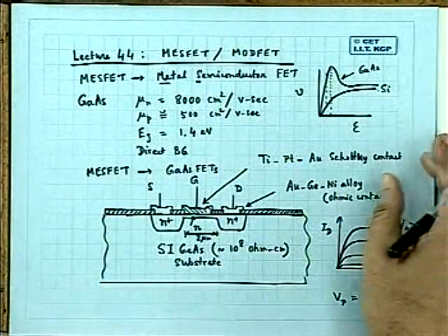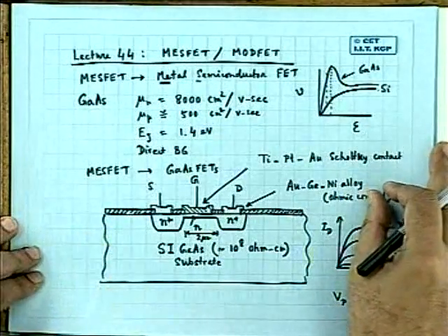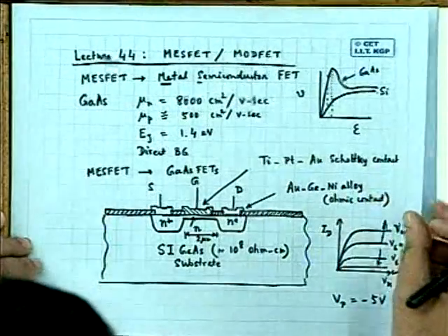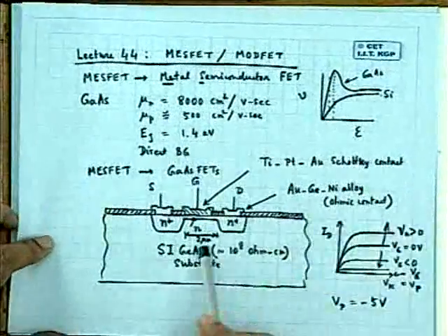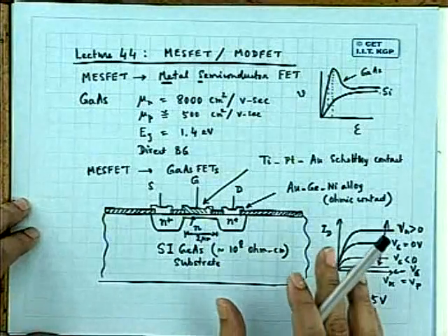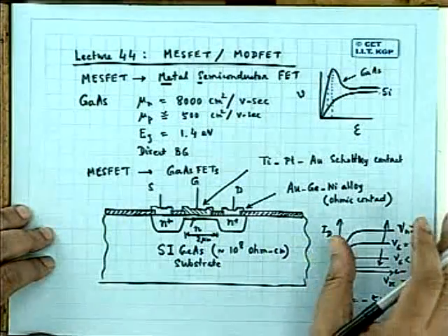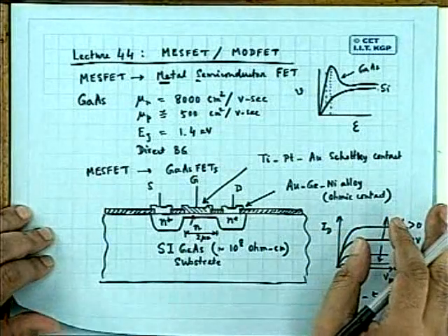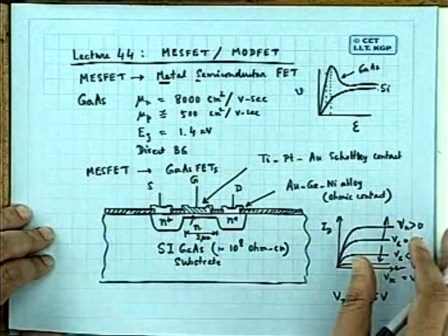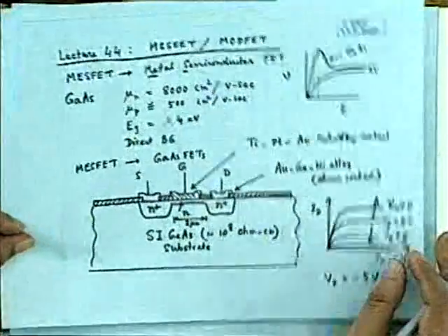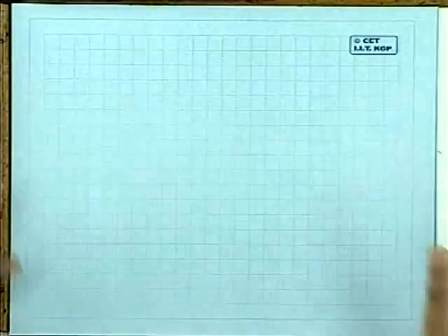So silicon people are very happy that gallium arsenide came and became a challenge, but slowly silicon is still very important. Gallium arsenide is a scaled down technology. One can make gallium arsenide FETs which are conventionally much higher speed as compared to silicon. But silicon people are also working very hard. Germanium silicon structures, heterojunctions, silicon carbide, and all these heterostructures are pushing the silicon frequencies also to the hundreds of gigahertz range. I'm coming to that afterward.